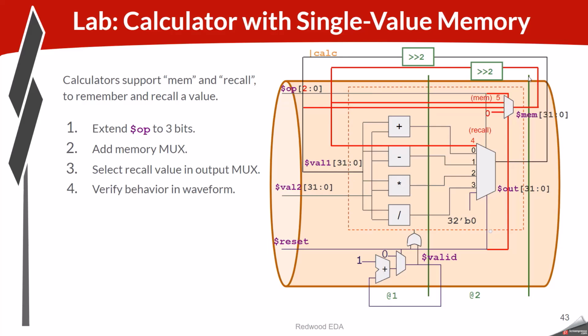This is a form of clock gating called functional clock gating because it impacts the behavior of the model. You can use that clock gating to avoid updating the value in the flop. But anyway, that's all sort of beyond the introductory level here. We're going to be explicit about all these recirculations through flip-flops.